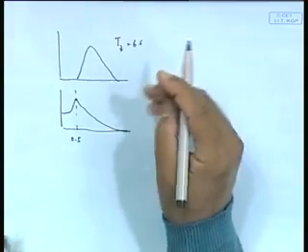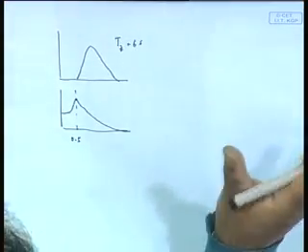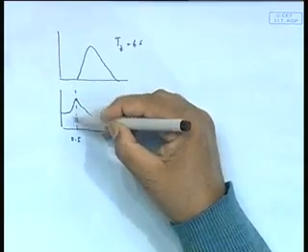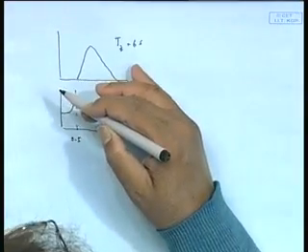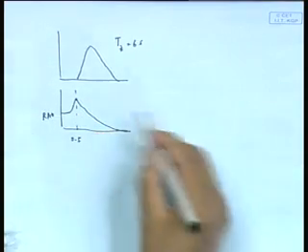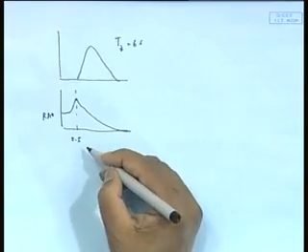Remember this omega, this is actually, let us say for an offshore structure, zero speed case, let us not complicate things. I just wanted to show you the tuning part, that why is it that it is not necessarily true that all bodies behave badly as the wave becomes bad. What is the correlation? The main point is that the frequencies at which your ship behaves worst should be the kind of waves existing most in the wave, then only it will be very bad. Now, in this particular case, this is my RAO, which does not change of course, because this particular boat has a resonance at 0.5 omega, which means 2 pi by 0.5 gives you about 12 seconds or so, right.